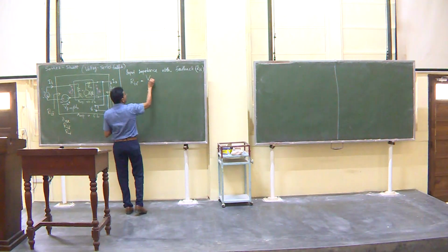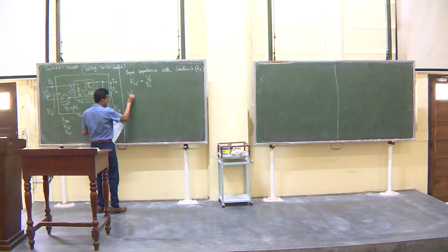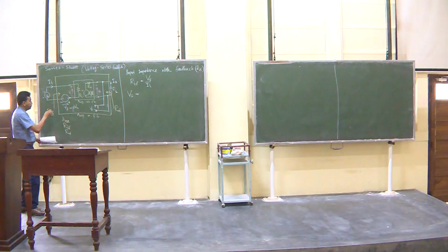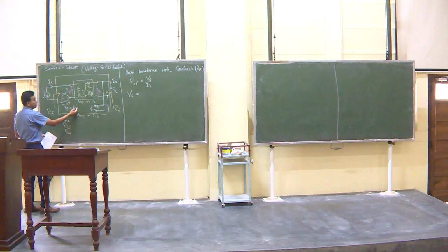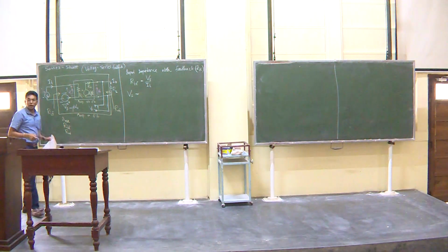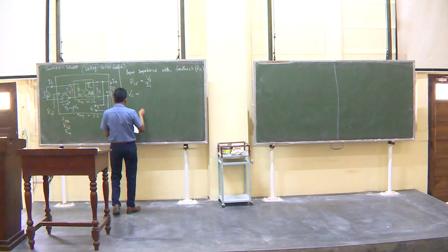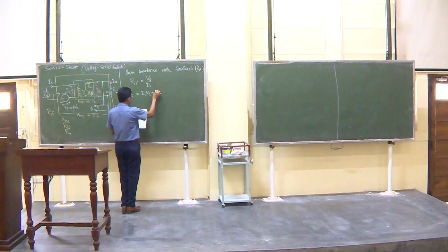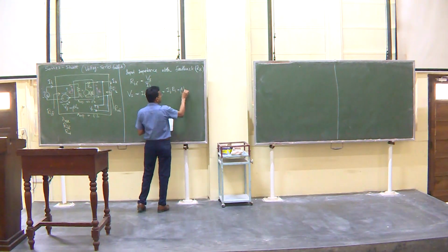That is Vs divided by II. But we know Vs is equal to, I can use Kirchhoff's voltage law to find that voltage, is equal to this plus that. This is equal to beta times V out, Vf. Vi is equal to II times Ri. Okay. So, therefore, I can write Vs is equal to II Ri plus Vf, which is equal to II Ri plus beta V out.